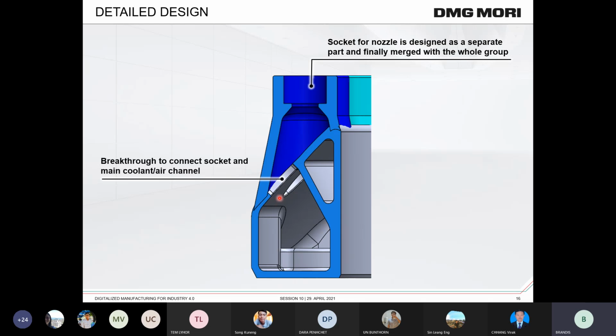It's the larger one. And we have here a second channel for pressed air, it's the smaller one. And so they are integrated in one body. And you can see here in the cutout that we have surfaces with angles to the bottom surface of more than 45 degrees. So it's possible to print such a geometry without support structure in the inner channels, because again, it's impossible to remove such a support structure there.